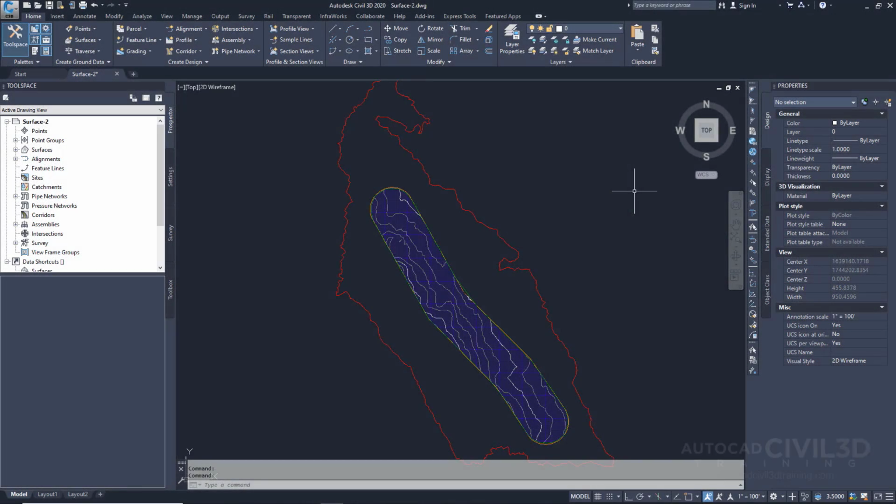In this exercise, you will use the point removal method of simplifying a surface. This method randomly selects points from the surface and reduces them based on the point density at different areas of the surface. More points are removed from areas in which the concentration of points is very dense than from areas that contain fewer points.